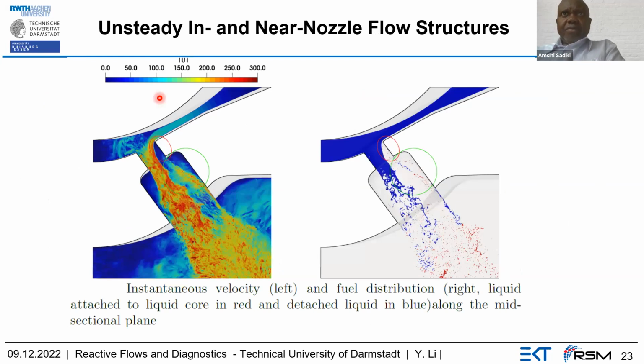The first part was to see how the velocity field evolved, and we see here that we have an augmentation of the velocity field in this area, because here we have a kind of recirculation and the velocity is very low, and it grows and then expands, in interaction with the droplets which are produced. Then, as we know, there is interaction between the two phases, and the droplets also reduce their velocity.